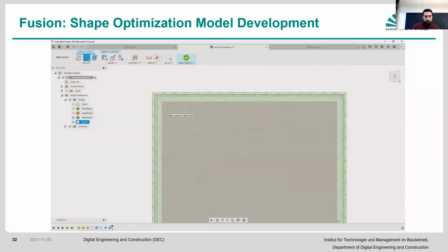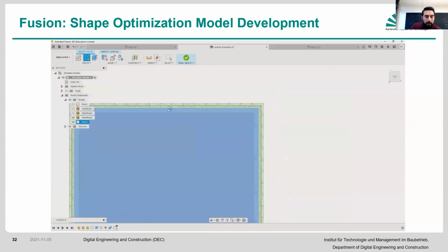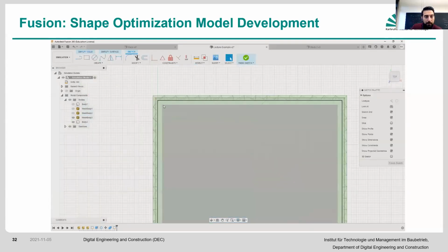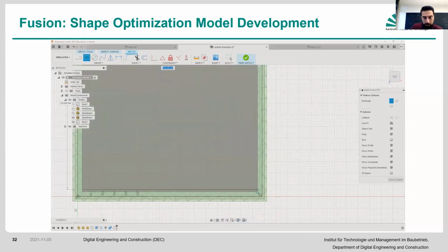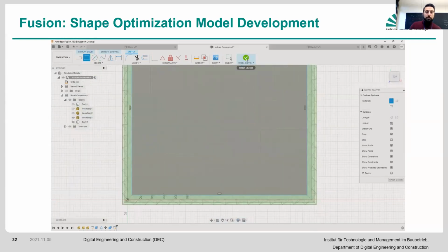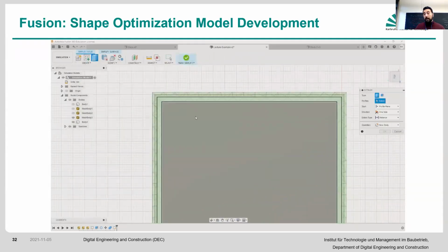You do create, you select the surface, which is anything on the top would be the surface that you want to start your sketch. Then you again go into the rectangle command. And then from the inside. And then once you have the inside there, then you go and extrude it, this one downwards.